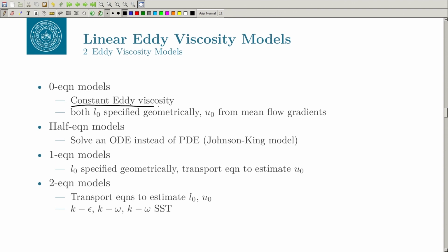So, just by the information that eddies contain energy, the mixing is much higher than the normal laminar viscosity. So, you can take the viscosity as, let us say, 10 times the laminar viscosity or 50 times the laminar viscosity and see how the performance is.